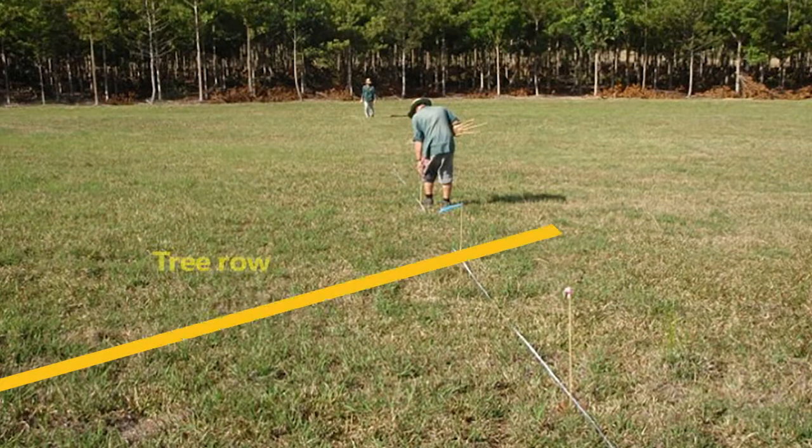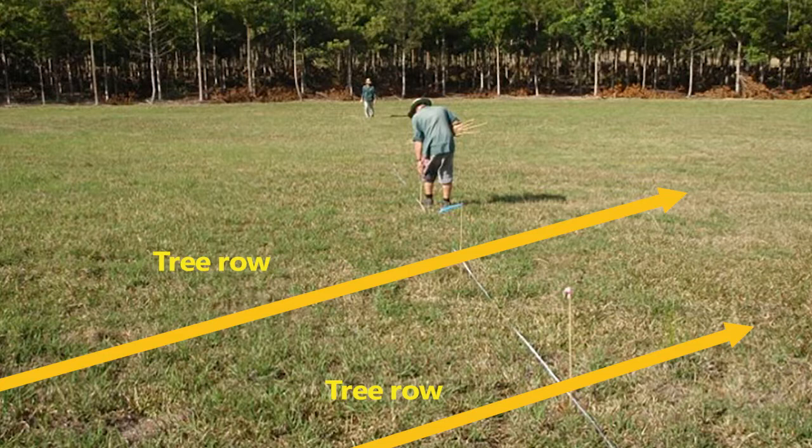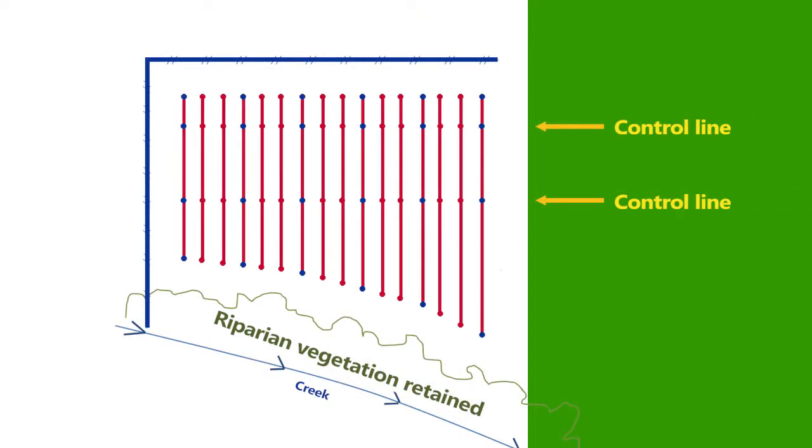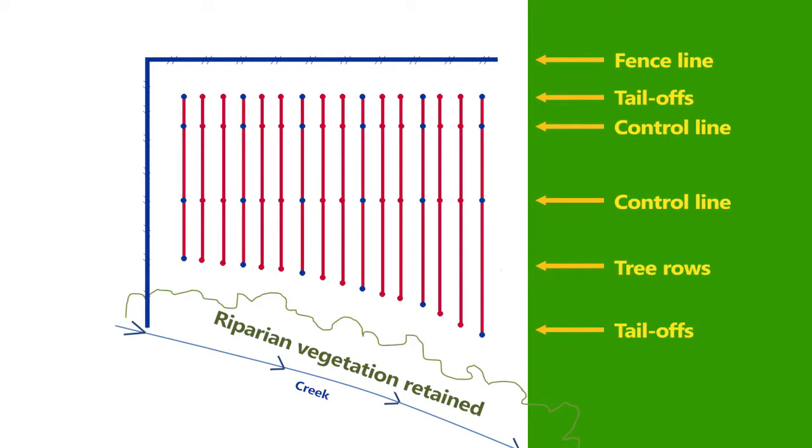The plantation design is marked out so that individual rows can be sprayed with herbicide in preparation for cultivation. One method of marking out involves the use of bamboo stakes placed at 4 metre intervals in a control line that runs perpendicular to your row direction. The stakes represent the centre of each tree row. By establishing 2 control lines at an appropriate interval, you can sight through the corresponding bamboo stakes to mark the beginning and end of each row.